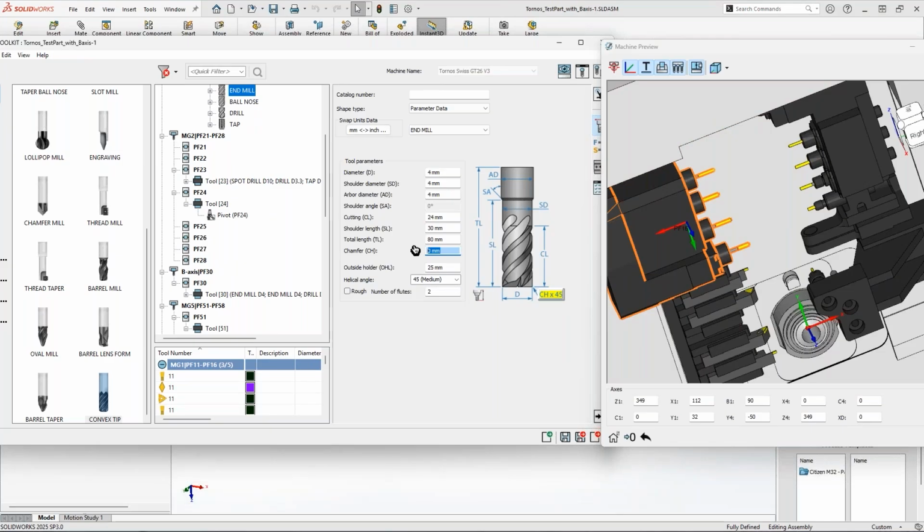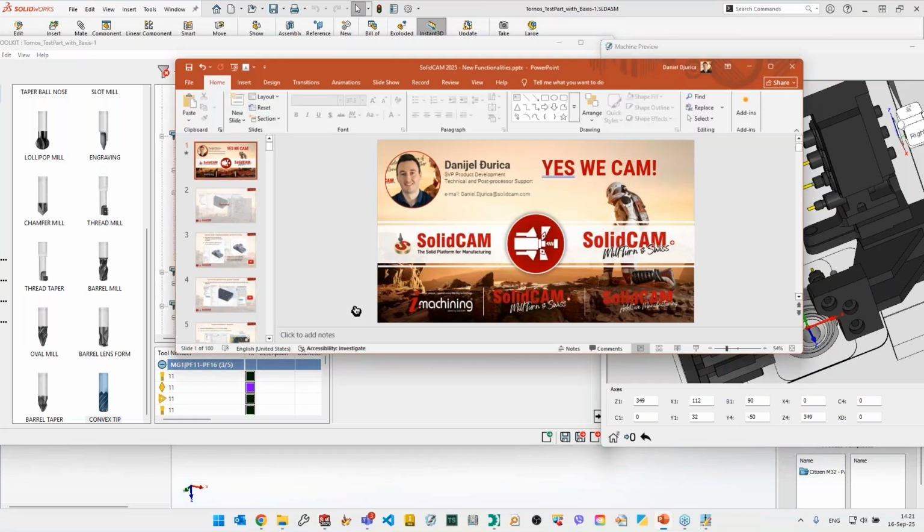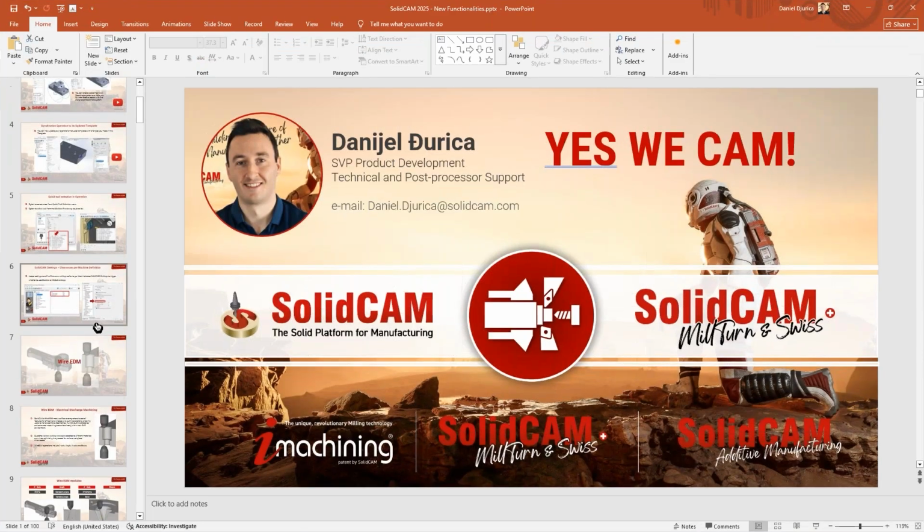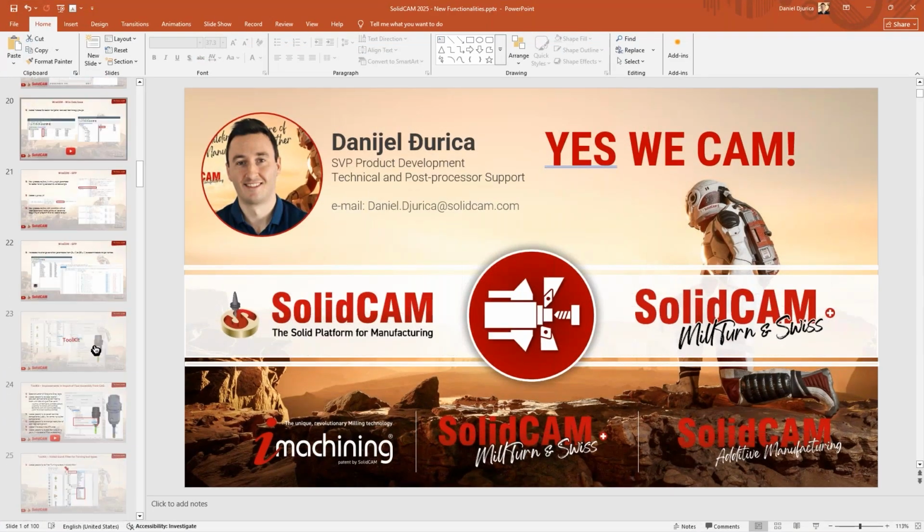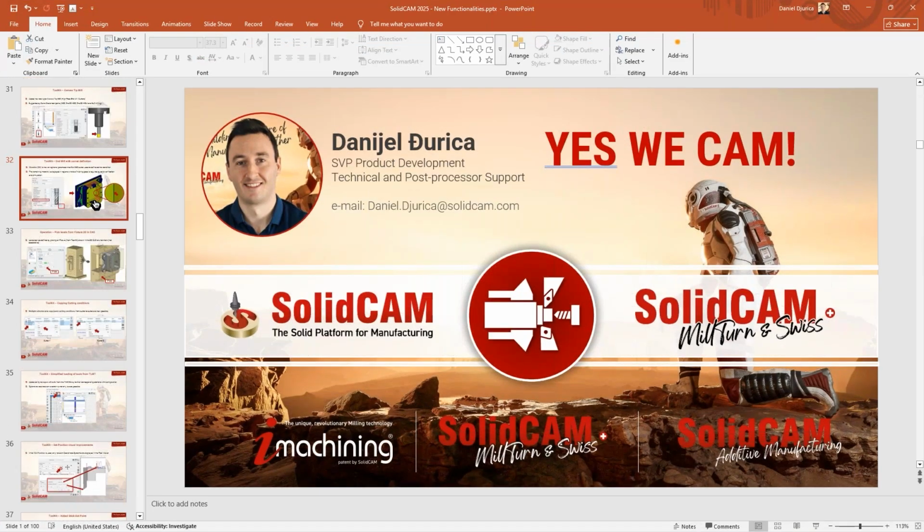And what is the main purpose of this parameter? When you put the real conditions of your real cutter here, that will also make your updated stock correct. So you could really see the most updated stock that needs to do additional finish. And I think I have in my presentation actually a very nice picture about this that I want to show you in this webinar. And it's here exactly.